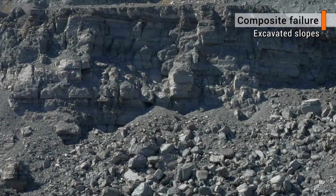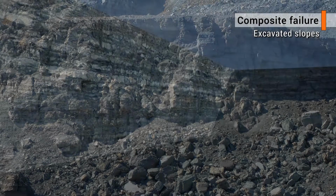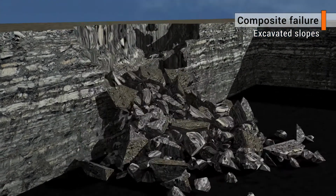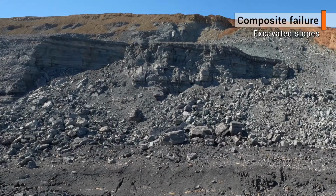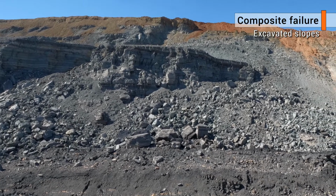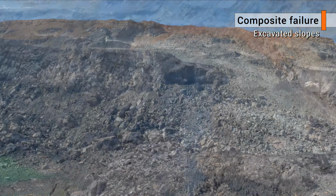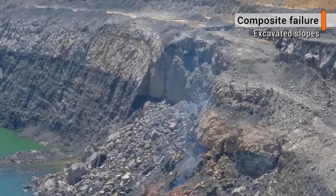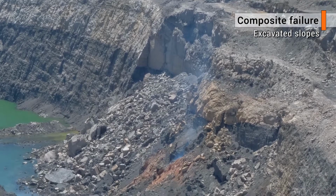Composite failures. These are typically the most common type of failure in excavated coal mine slopes. Composite failures involve a combination of planar, wedge and toppling failure modes along persistent defects, and also some component of rock mass fracturing and failure. Typical composite failures are vertically to subvertically bound by structural defects and horizontally bound by a weak, generally carbonaceous layer. Such failures occur at both the individual bench scale or as a failure of the overall pit slope.